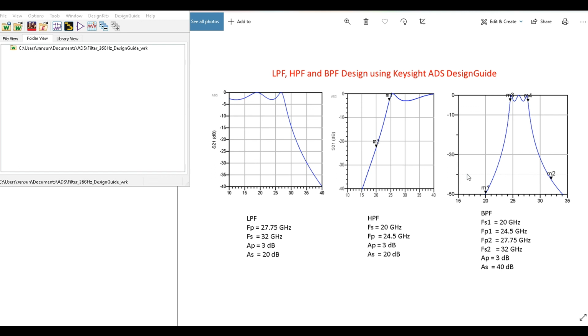All you need to do is know your values. For example, for the filters, if you have your cutoff frequency, you basically need to calculate what you want your bandwidth frequency to be. Bandwidth, for example, is at -3 dB. For example, you might say you want your stop band to be at -40 dB.